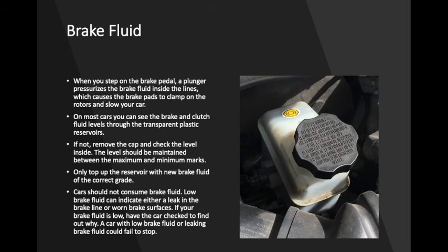The level should be maintained between the maximum and minimum marks. Only top up the reservoir with new brake fluid of the correct grade. Cars should not consume brake fluid. Low brake fluid can indicate either a leak in your brake line or worn brake surfaces. If your brake fluid is low, have the car checked to find out why. A car with low brake fluid or leaking brake fluid could fail to stop.